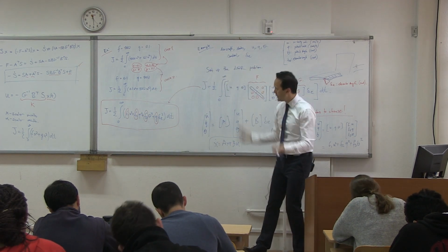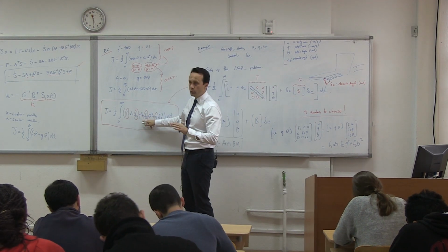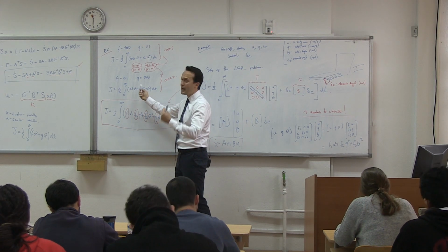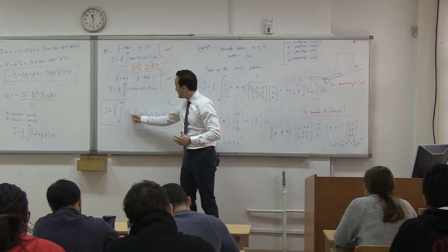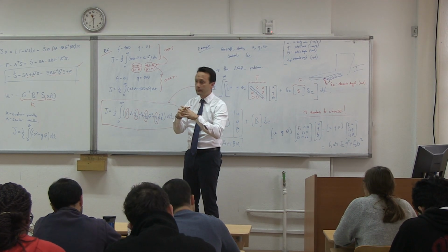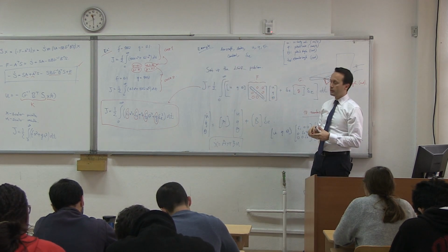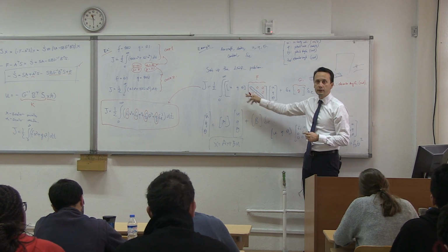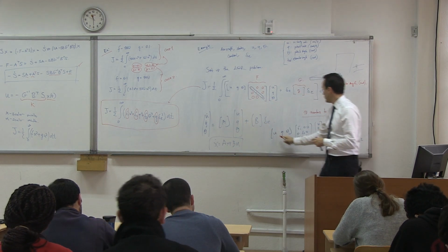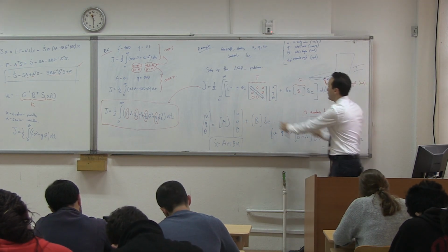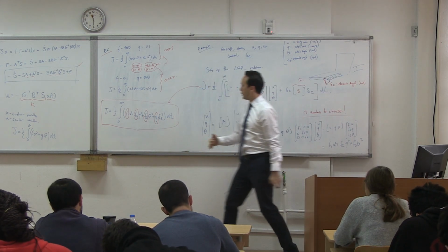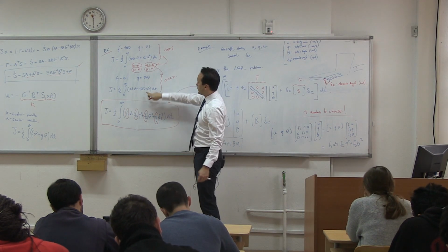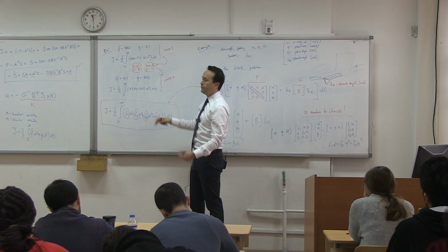And now you actually have the freedom to say U is more important than Q, theta is more important than del E. Now you have a weighing not only between the U and the x, you actually can weigh now the states between them by choosing these numbers. You understand that? Zeros, zeros, and you have the diagonal, and that will turn into this. And if you write this, this is now your optimization problem. So just like the argument over here, where you had only 2 numbers, now you have 4.